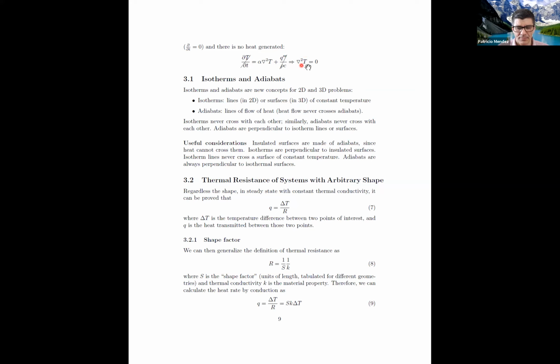Now, clearly the solution for a cylinder is not the same solution as a sphere, not the same solution as Mickey Mouse. And the difference, why the same equation can give different solutions, is in the boundary conditions. So in heat transfer, the key is in the boundary conditions. The differential equation itself became very simple, but when we put the boundary conditions in, it might become very difficult to solve. So we can say some things about the final result